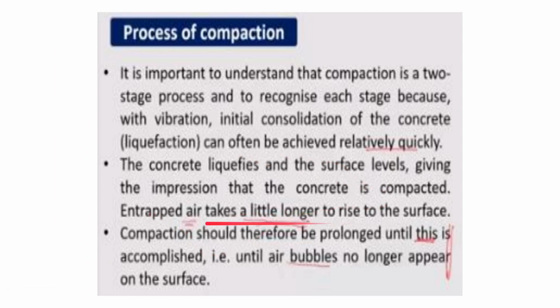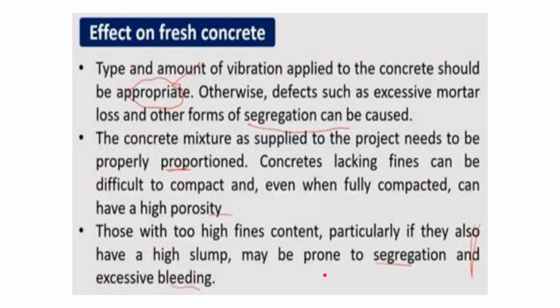Entrapped air removal is the second stage, and it takes a longer time because the air takes longer to rise to the surface. So compaction should therefore be prolonged until this is accomplished, that is until air bubbles no longer appear on the surface. So compaction should be done until no air bubbles are present or seen on the surface.